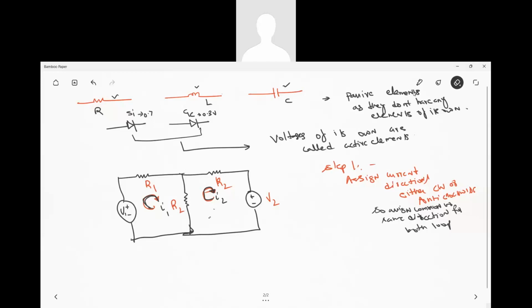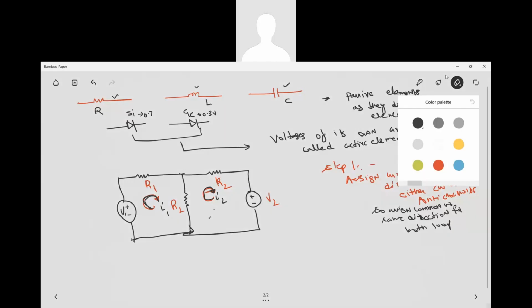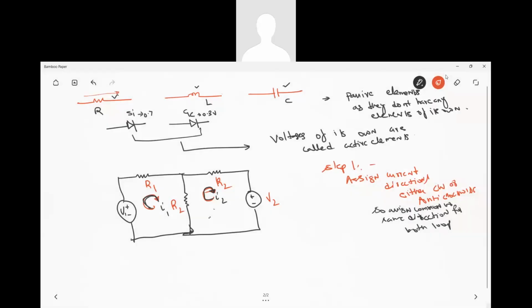Only this direction we have taken, not the other way around. Now, once you have taken the direction, what did I tell you? This resistor is there, na? Its polarity will get established by the current direction. So the current direction is like this, so it is going like this, and like this, and like this. Correct? So that means here it is plus, here it is minus.